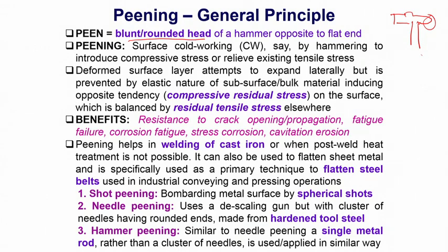And when you hit any flat surface with this kind of a rounded head, obviously it is going to create certain deformation, and that will be a diffuse deformation. When you deform, you create a deformation zone underneath, and that particular zone, if it is a metallic material, is likely to create a higher density of dislocations, and also because of the recovery process, there will be residual stress developed, which is compressive in nature.